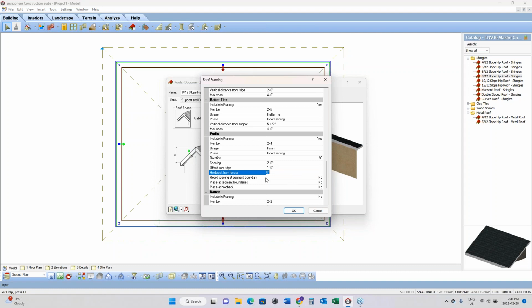When you have a multi-surface roof, with lots of hips and lots of gables and all different surfaces in a very complex roof, every time you hit a different surface, you can reset the spacing. So I'm coming along with my 2 feet, and then I hit another surface. Do I reset it if the ridge sits higher in that section? Or do I say, no, just keep running it through all at the same heights all the way through the roof? So we could set that to no.